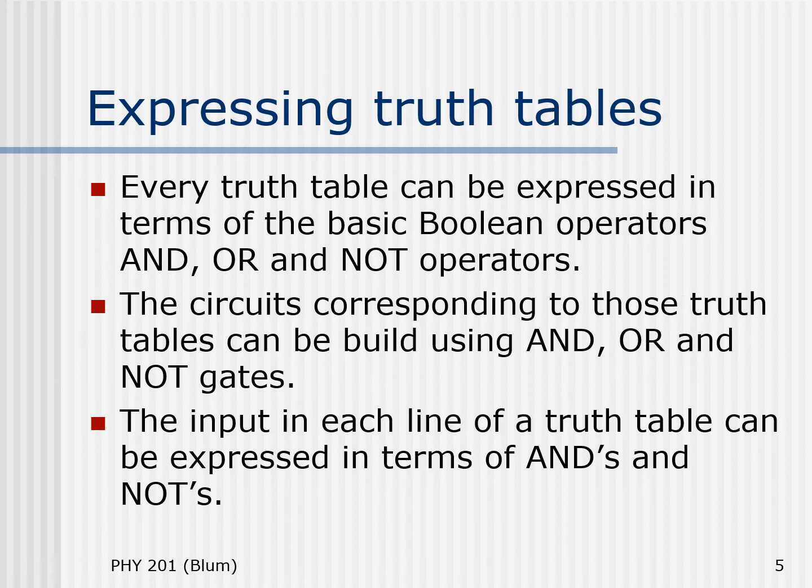So what we want to do is learn how to express any truth table in terms of Boolean operators. We will use and, or, and not, and then we can have the corresponding logic gates and, or, and not, and then we can build the corresponding circuits. There are different ways to do this. We're going to start with an approach that builds up from the idea that any one line of a truth table can be expressed using ands and nots.